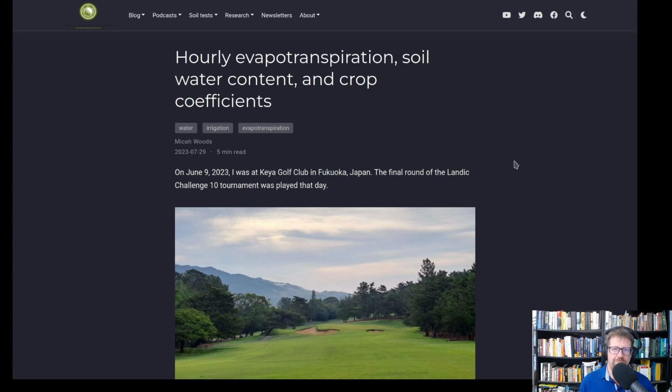And if you compare that water use rate of the grass as a depth to your evapotranspiration, you can then find out what your in-field, real-life, site-specific crop coefficient is, which is, to me, really cool. And that is another useful thing that we can do when we start switching between these measurements.